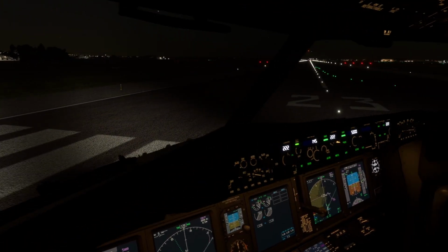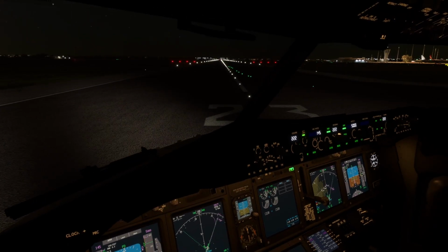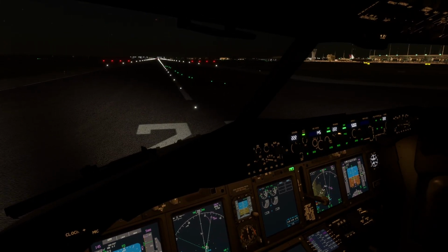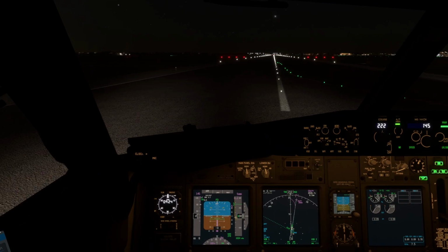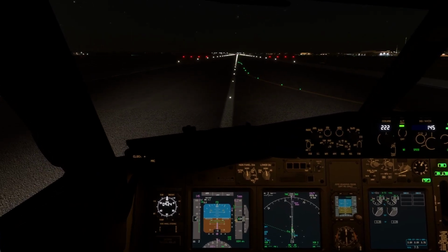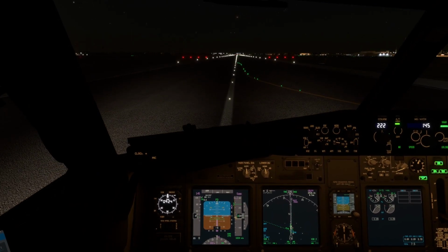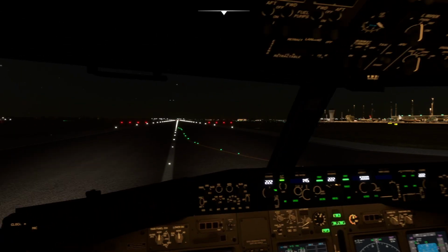You sit in the aircraft, you sit in the cabin, you hear that high pitch whirring, and you're like, okay, electric hydraulic pumps. Okay, these are the fuel pumps. Oh, okay, engine 2 started and then packs came on. Oh, they're doing isolated pack start. Oh, the lights just flickered, bus transfer, switches were flicked.